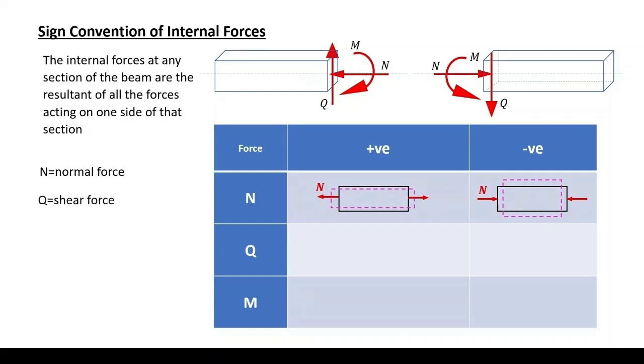Shear. Our element, we have the shear force applied perpendicular to the center line. Positive shear has the left force heading upwards, and this is the deformation under positive shear. Our element, negative shear with the left force heading downwards and the deformation expressed in the purple dashed line.